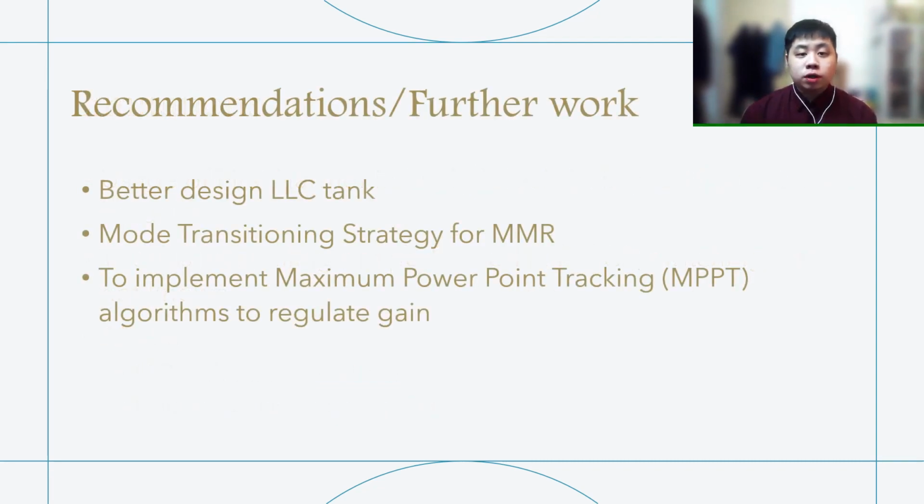There is much more work to be done even after my project phase ends, such as to improve the LLC tank parameters in the design, to introduce a mode transitioning strategy for the MMR, such that the transition is not too sudden, and to implement MPPT algorithms and thus regulate the gain based on the input voltage.